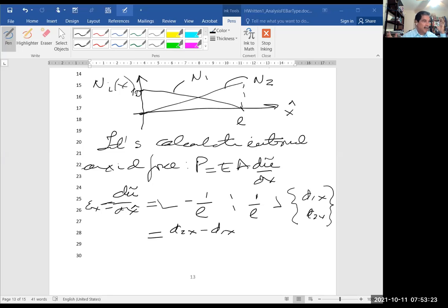Okay, I'll try to solve it. Let's do our best. So what we're saying is that we differentiate. This is an approximation. That's something that we learn basically. These are constants that we're trying to determine. So we make this product and we obtain that divided by L. And you see that's basically the elongation divided by the original length. That's basically the definition of the strain. Okay? So I wanted to show you that.